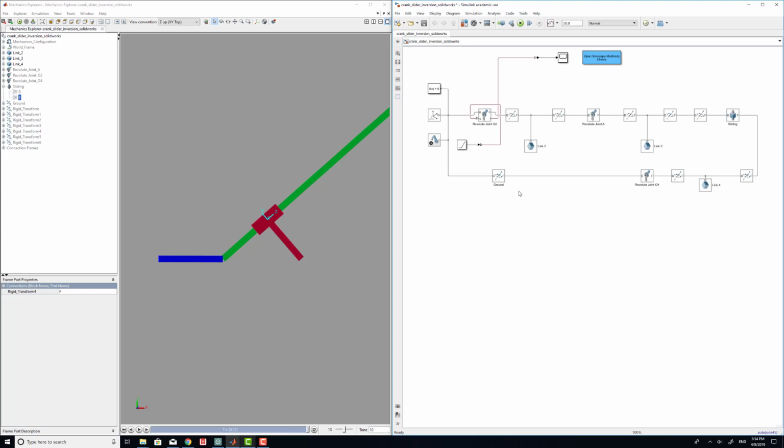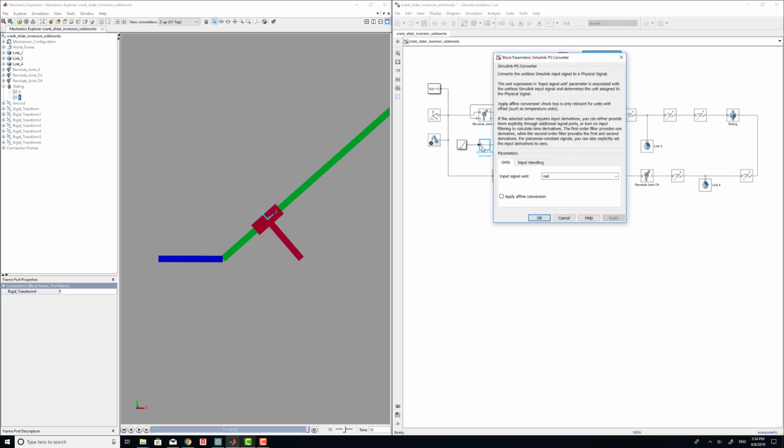The reason why we got this high spike is because of this filtering. In MATLAB, when we create a ramp function at time equal to 0, this filtering would not work very well because there is a sharp turning point in your function, and at that point, the function is not differentiable. In order to smooth out these numerical errors, we need to change the filter derivatives to provided by inputs.